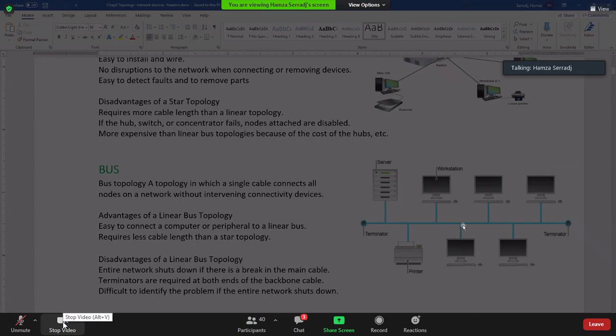This data will be sent here and here and here, until we find the identifier of the destination device that is going to answer. But as all the others received exactly the same message, it will also be sent onward again and again. So we're always going to have a signal going back and forth. This is why we need a terminator. So when anything reaches those devices, it will be killed, right? The signal will be dropped.